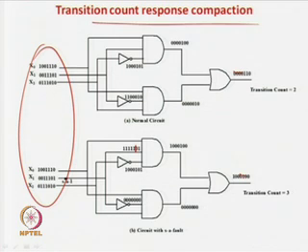which you can decide by the random patterns generated by your LFSR design. Now you have to find out a compaction scheme. Then you have to find out which are the most important faults, and which are getting detected and which are not getting detected because of the aliasing effect. Then accordingly you find out your coverage and you do your design. Basically it is a multi-criteria optimization problem, as you can see.